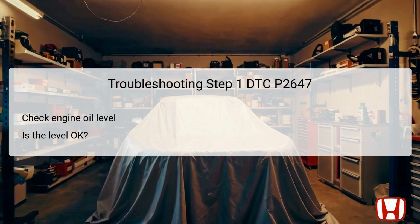The initial step in troubleshooting DTC P2647 involves checking the engine oil level, which is critical for the operation of the rocker arm oil pressure switch and the overall VTEC system. Adequate oil levels are necessary to ensure proper lubricity and pressure within the engine. Therefore, this step cannot be overlooked. It is essential to verify that the oil level is within the recommended range indicated on the dipstick.